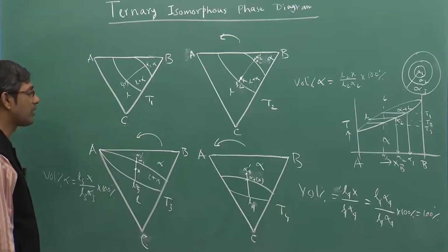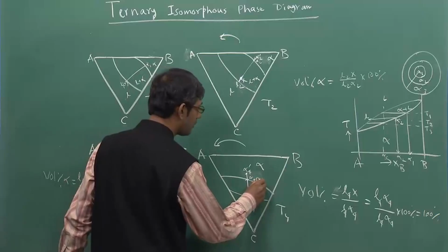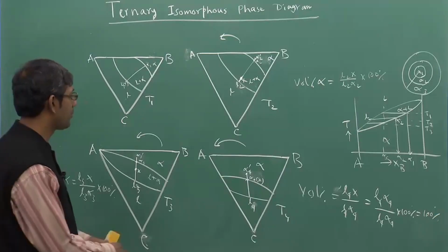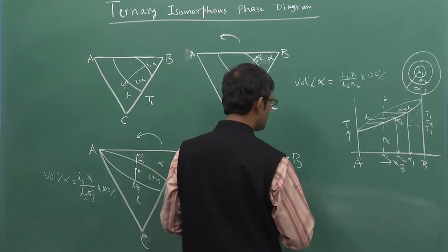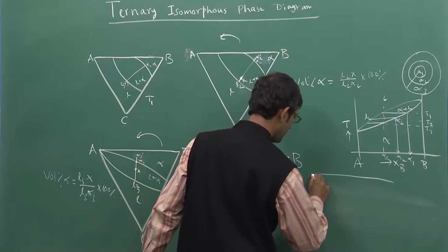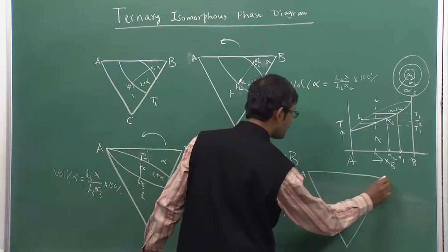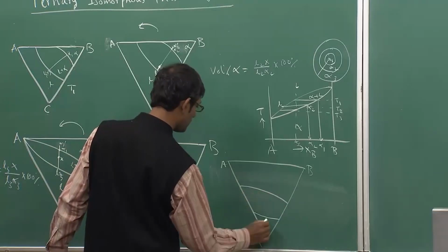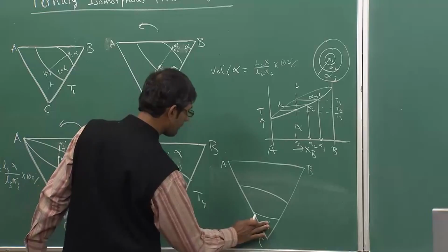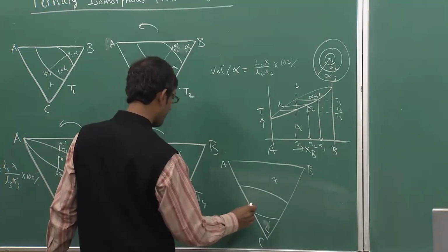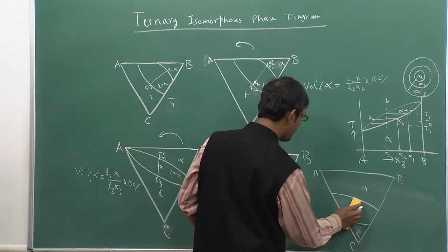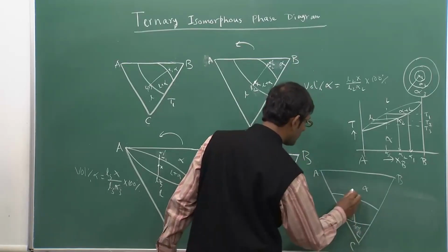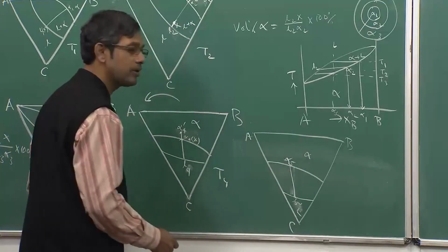As you clearly see, the solidification will not get over at alpha 4 or T4, it will go down actually to a temperature lower than T4, okay. And probably I need to draw another section, and this will be a little bit down. Oops, it's a little bit angular. So this will be some L5 alpha 5, correct. So that is what happens here also.